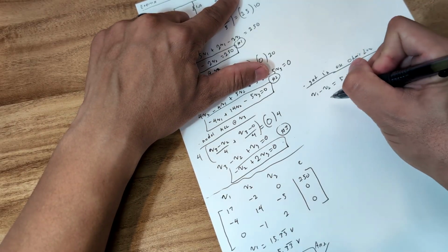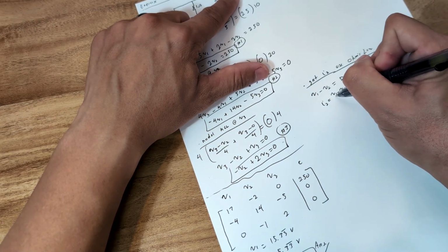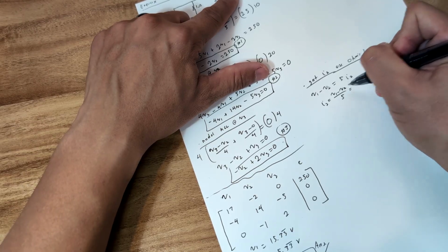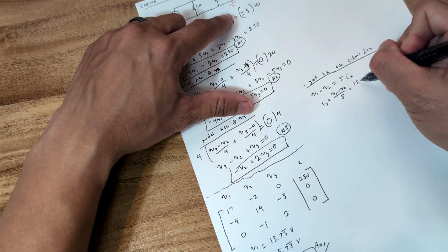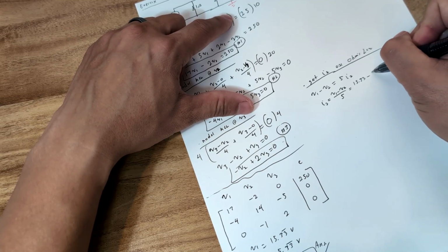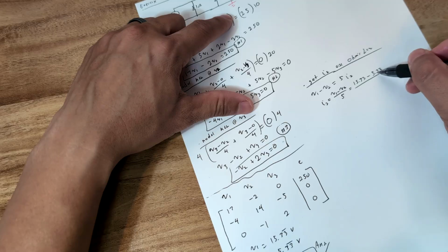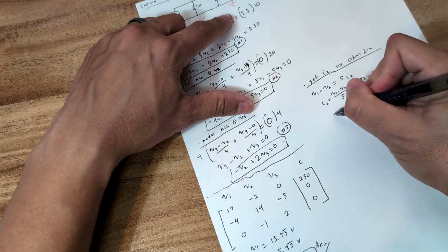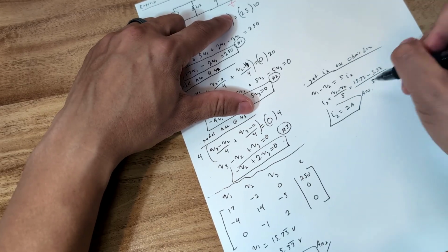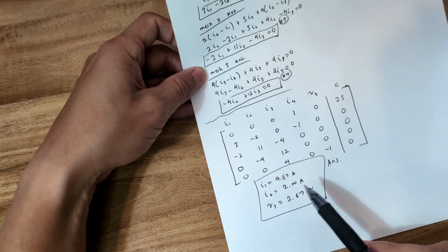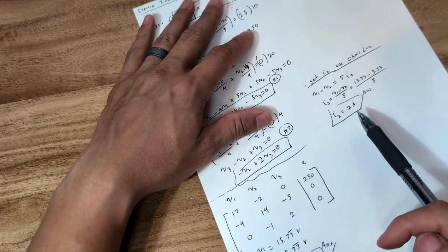We'll go step by step. V1 minus V2. You could skip this easily if you wanted to, but I like showing the steps, especially showing the professor that I know what I'm doing, and maybe you can get partial credit. So V1 equals 15.33, and then 5.33 is V2, divided by 5, which you'll find that I2 is equal to 2 amps. That is one of our answers, which is consistent with our previous analysis using mesh, 2 amps. I2 is 2 amps.